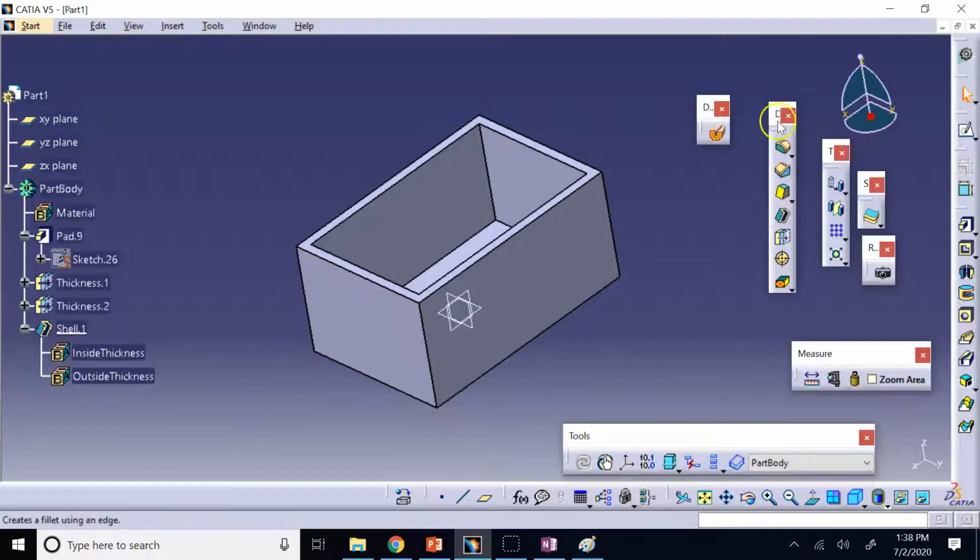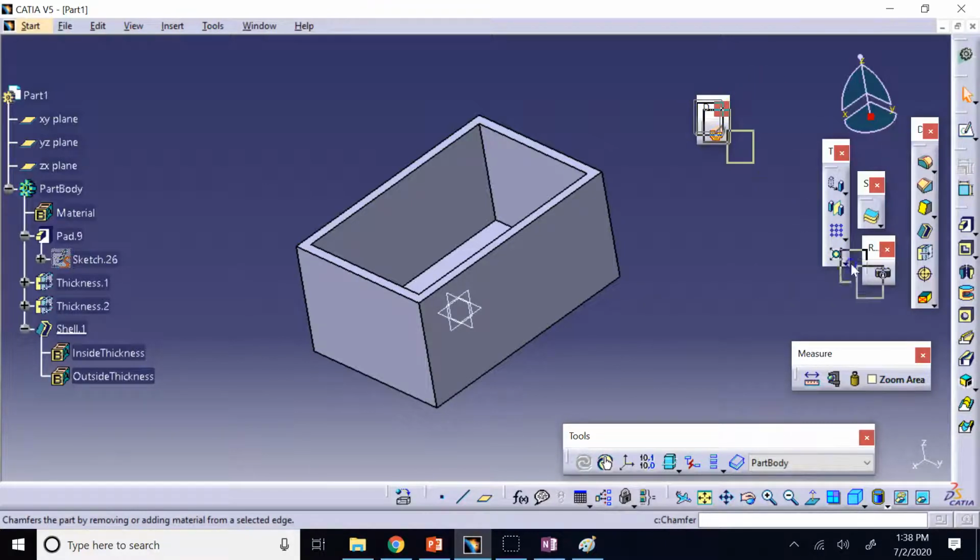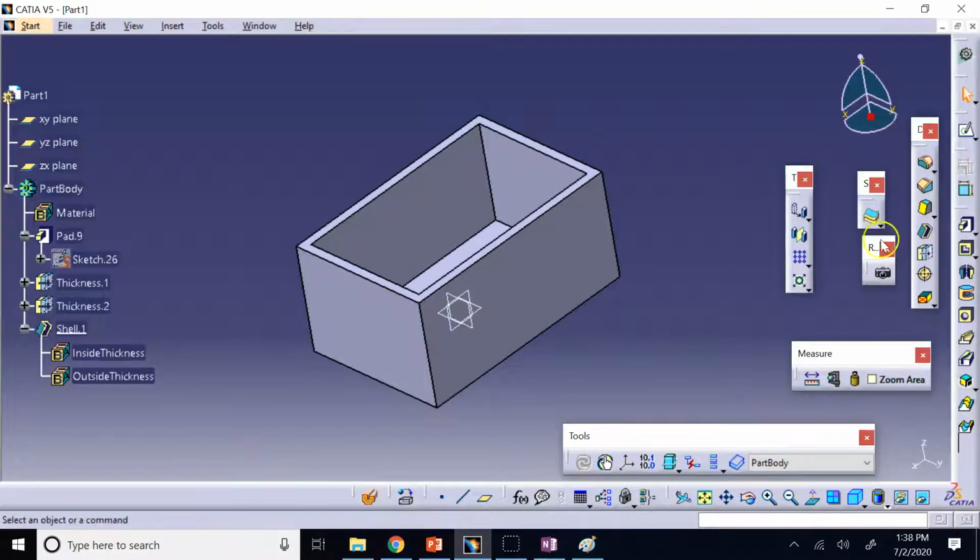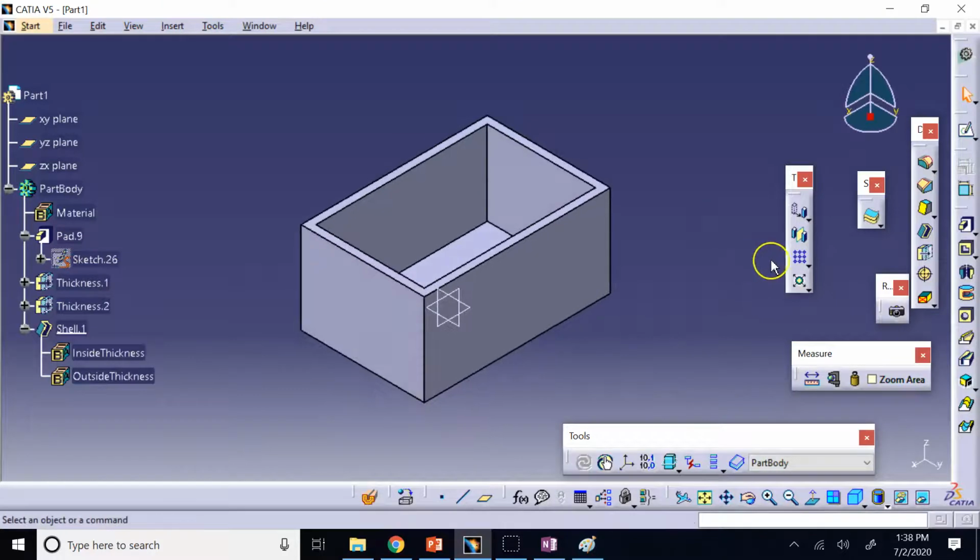So now I assume that you have seen this guy here and this one, which is really good. There is this toolbar left we need to talk about, and a few more. So this transformation toolbar is an interesting toolbar. So you can do a lot more complementary actions on your part. Like what? Like, for example, you can mirror a feature or the entire part. You can translate, you can rotate, or in general, axis to axis transform of a part.